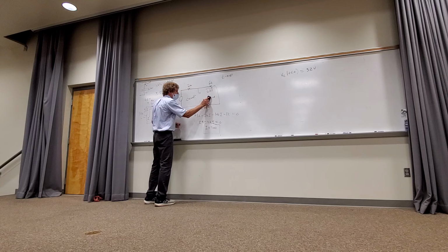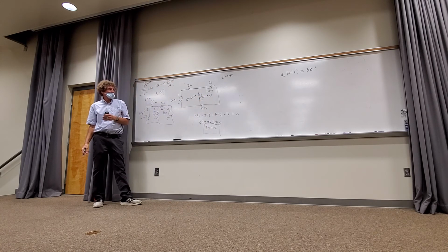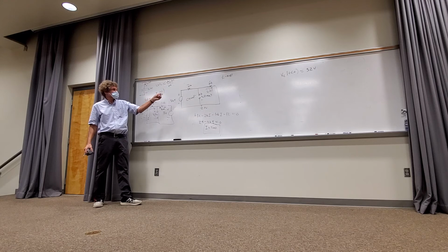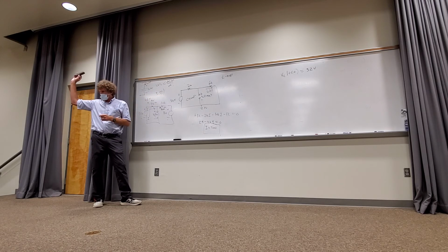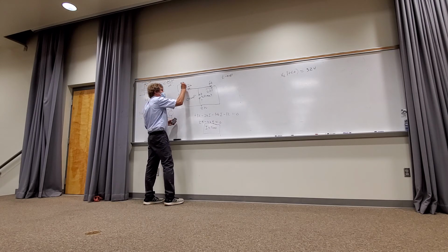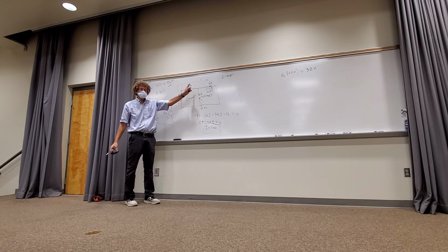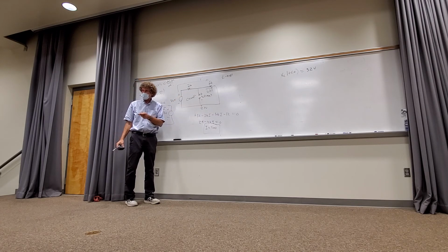So it looks like this, as t goes to infinity. All right, what's the voltage across that as t goes to infinity? Just take a look at that. How many see that you have 2 resistors in series that current can flow through? Y'all see that? Current can flow this way, right? Can flow that. It can't flow through the center because it looks like an open circuit. Do y'all agree with that?